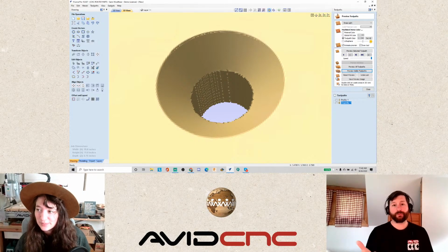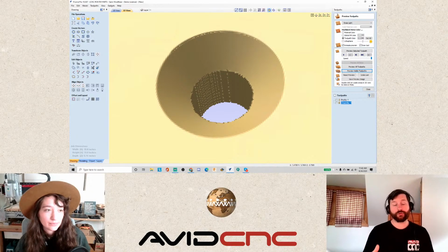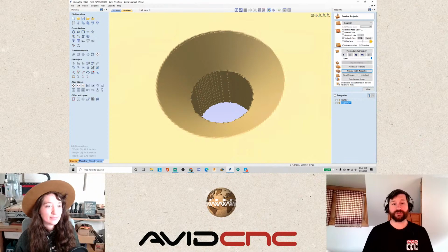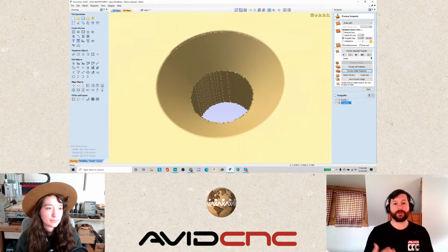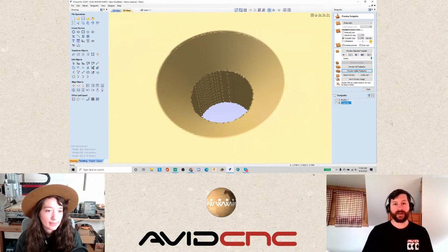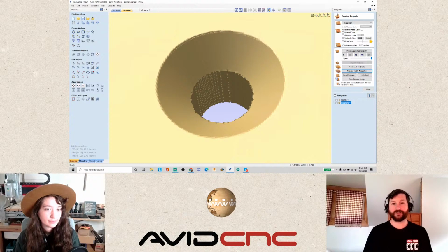Yeah, but more importantly, I think, Sami, understanding what knobs in the tool database we want to adjust and where our baselines are, because even though we're in a material we are aware of and we know some of the settings, reviewing those and making sure they're perfect for the toolpath vectors that you're trying to create is always something that I'm going to encourage people as a double check. The better diligence we can have in the CAM area of our toolpath creation, the easier it is to be an operator. Right.